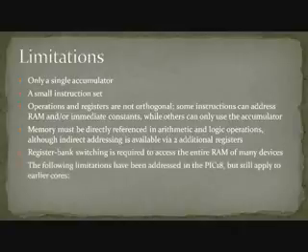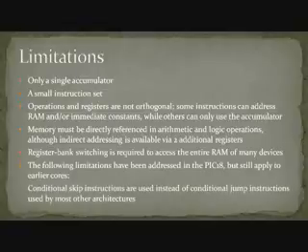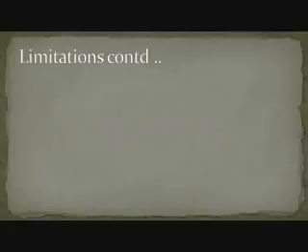The following limitations have been addressed in the PIC 18 but still apply to earlier cores. Conditional skip instructions are used instead of the conditional jump instructions used by most other architectures. Index addressing mode is very rudimentary.